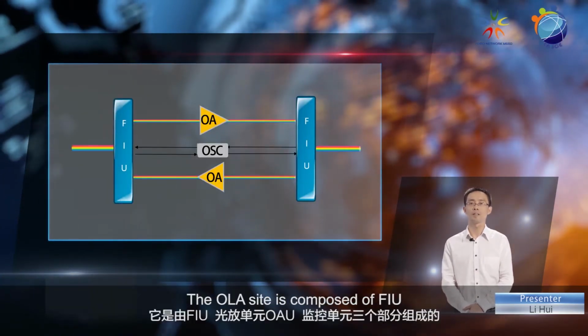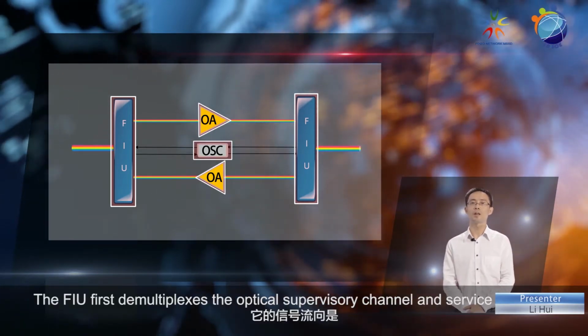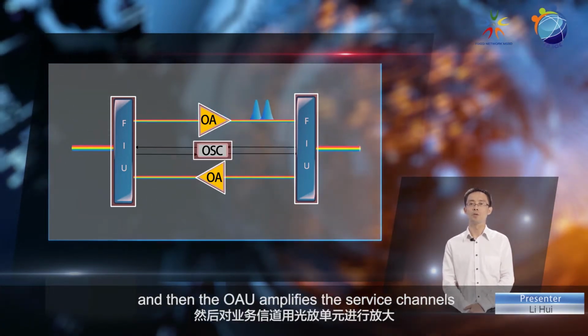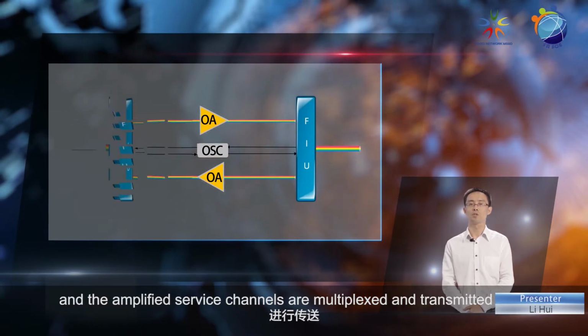The OLA site is composed of FIU, OAU, and optical supervisory units. The FIU first demultiplexes the optical supervisory channel and service channels, and then the OAU amplifies the service channels. Finally, the supervisory channel and the amplified service channels are multiplexed and transmitted.